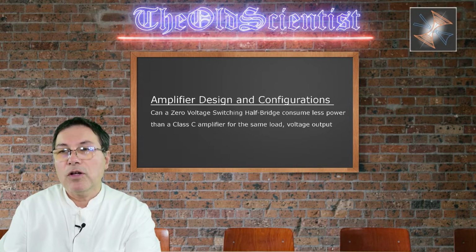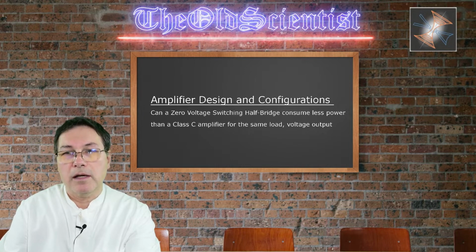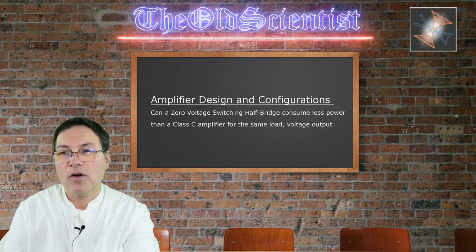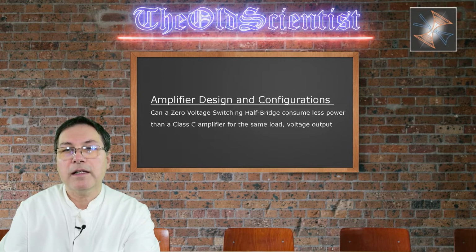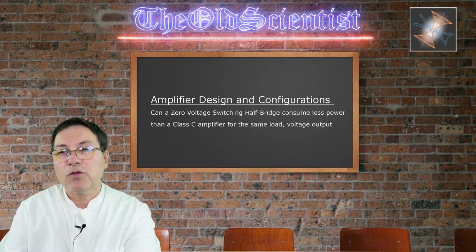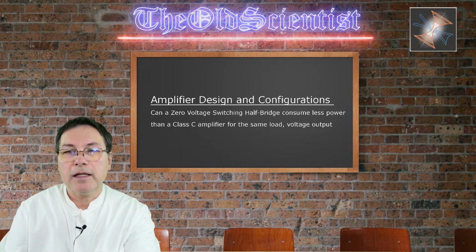My design, the zero voltage switching device, is a dual class C amplifier which receives each of the signals from a center tapped signal transformer with very high fidelity based on nanocrystal technology. We have twice the components we need to energize. My question again is, can we consume less power than a single class C amplifier to achieve 18.1 kV on a secondary on the flyback transformer?